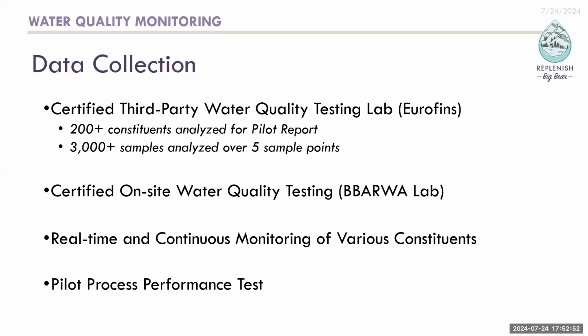You have a question, Greg? Does the testing of the staining tell you the lifespan to expect? Are you referring to the staining of the RO membranes? In a way, yeah, it tells you how aggressive that water was on the membranes. And you can get a sense for whether the expected useful life estimates for those particular technologies are on par with what we're actually seeing. You probably saw, I think we included some of the specific microscopy images. So yeah, it helps you understand what type of scaling and what type of biofouling you're getting on those membranes.